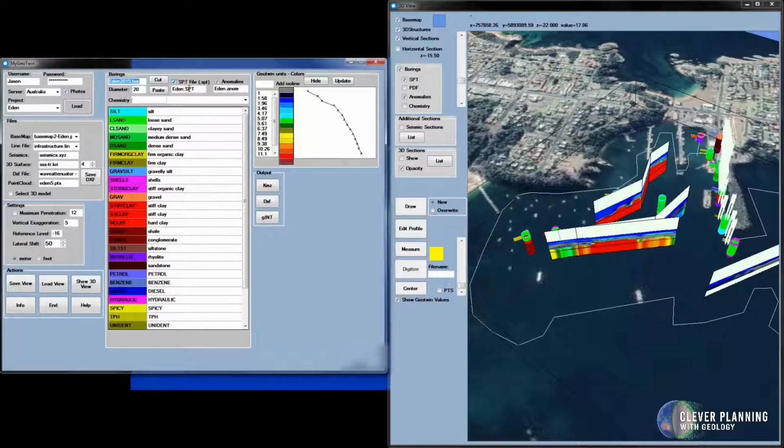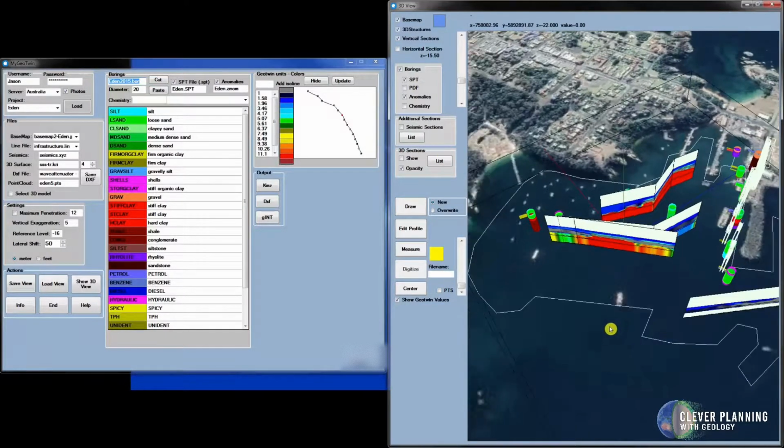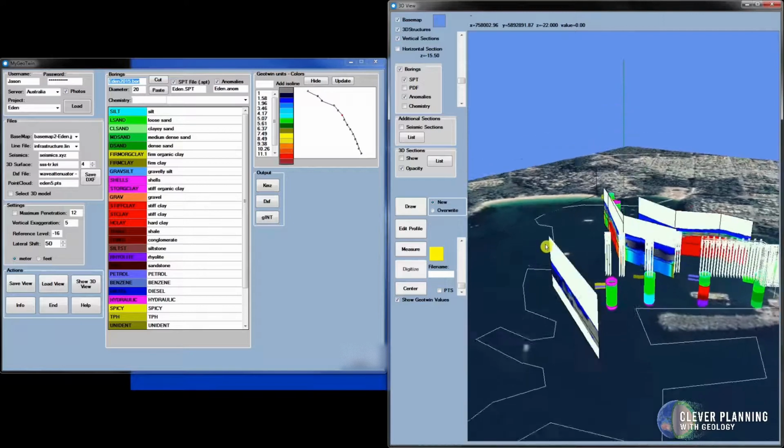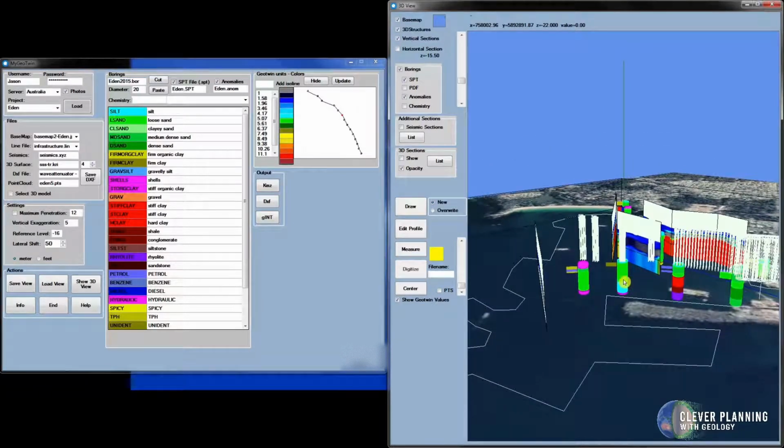Downhole data such as SPT or anomaly data may be available. SPT data is in blow counts and bracketed in units of 5 N counts. Anomaly data would normally be just on-site observations and unitless. Anomaly data is reported on the bar above the model as shown.